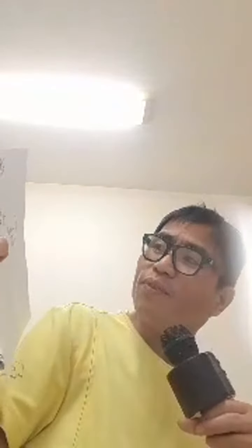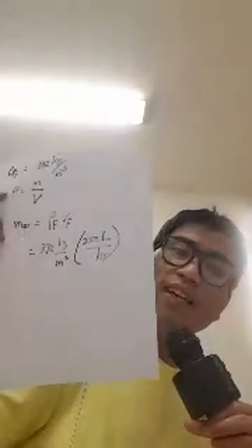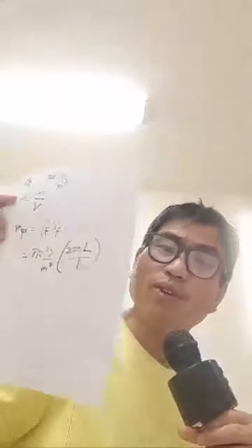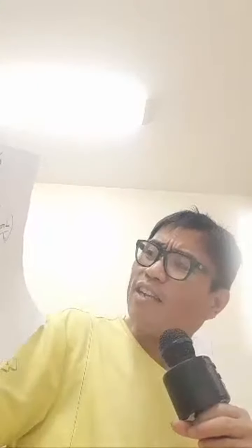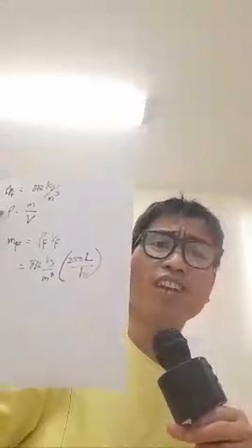Okay, so we have density is equal to mass over volume. And then, right, density of the feed times the volumetric flow rate. Now, since I used the density of 1,000 kilogram per cubic meter of water for the formula in the specific gravity, right? Now, we have a problem here because there's a mixing of the units. So we have 872 kg per cubic meter as the density times 2,000 liter per hour. We have to cancel that, guys. One is cubic meter, the other is liter.